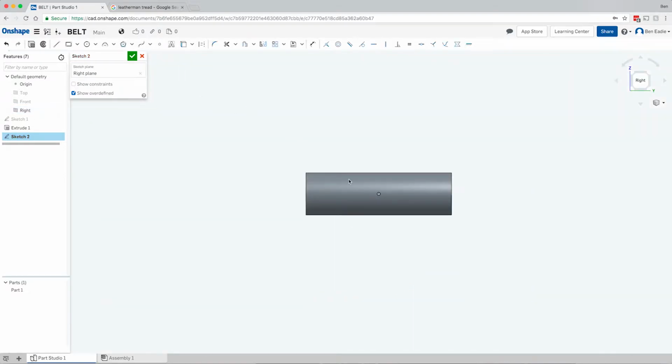So there are a few different ways that we can draw the hexes. One of the easiest ways to start out is, again, I like to have some reference geometry. So I'm going to click on line. Now you'll remember before that I drew the line out in the middle of space, and afterwards I hit the construction geometry. But here's something that's kind of neat: I can hit construction and line at the same time, and it will allow me to draw a construction line straight off, and I don't have to come in and do any more of that.